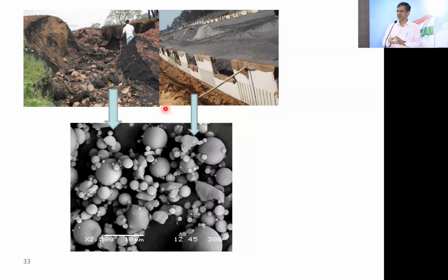So if you can analyze, it will be convincing. So without looking at the site, I agreed. Okay, I'll do it. But by the time I reached, it was all sliding out. Then I asked, what is the analysis you have done? So that is the computer analysis. Computer analysis was around 300 pages. For the geo strip they put in, and this fly ash, the laboratory showed the friction angle between the strip and the fly ash is around 32 degrees or so. Accordingly they have designed for 32 or 40 degrees, and they have designed everything.